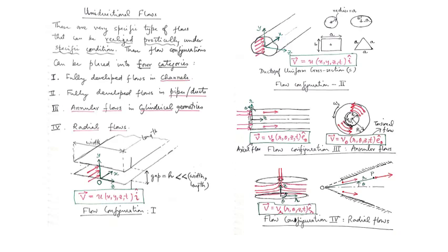So if you, for the time being, leave this inlet flow or developing flow region, then once the viscous layers from the top and bottom surfaces meet, and the flow becomes fully viscous in the entire gap, then we can practically realize a unidirectional flow where all the fluid particles are seen to move along the length of the channel, or along the x direction.